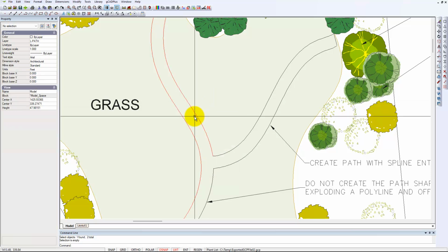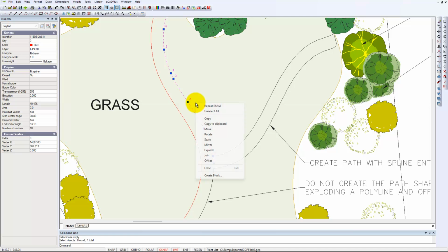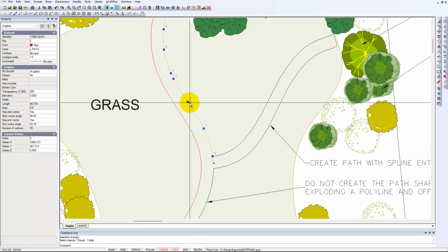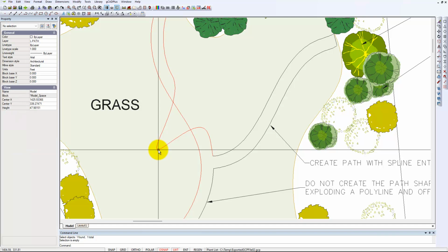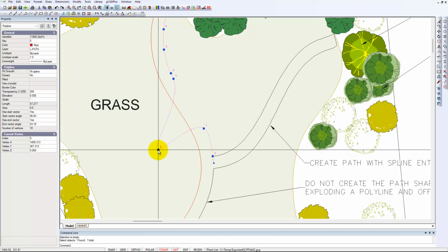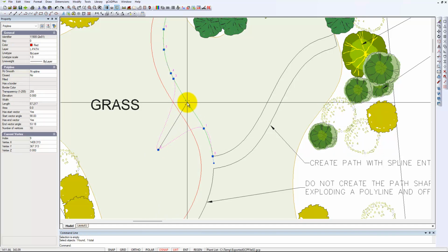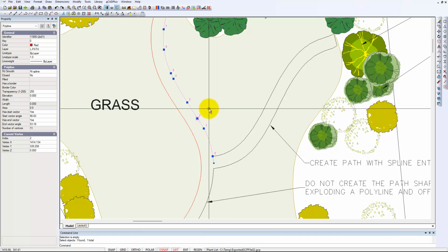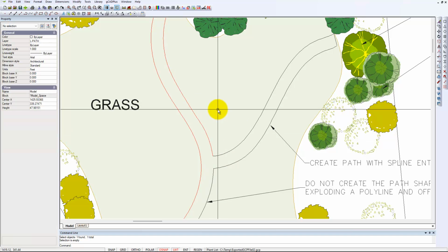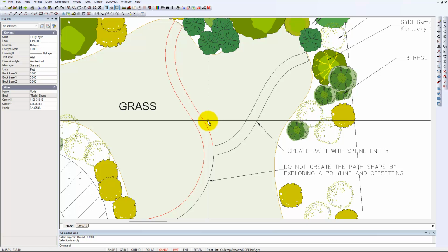You can't have 2 polylines selected, but we could make that one hot now. Input a coordinate, and whoops, I'm trying to demonstrate that I can insert a vertex here, so you've got more control over that flexible line. But I digress.